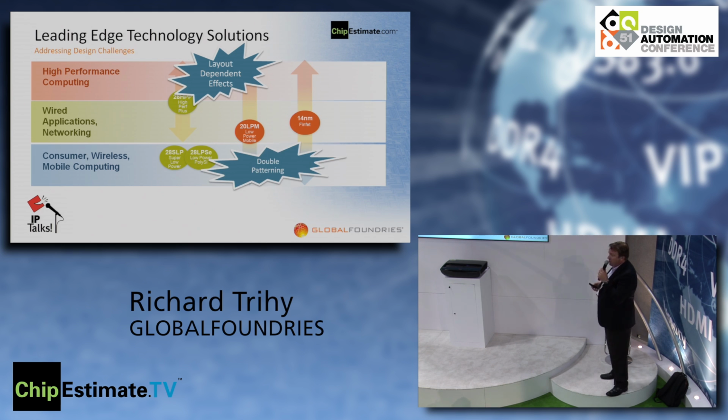We also have at 20 nanometer double patterning effects that impact every aspect of the design, and I'll go into a little more detail on that. And then finally at 14 nanometer there's FinFETs. And so FinFETs bring a lot of new capability, but they also bring a lot of constraints and restrictions that all have to be factored into the design phase.